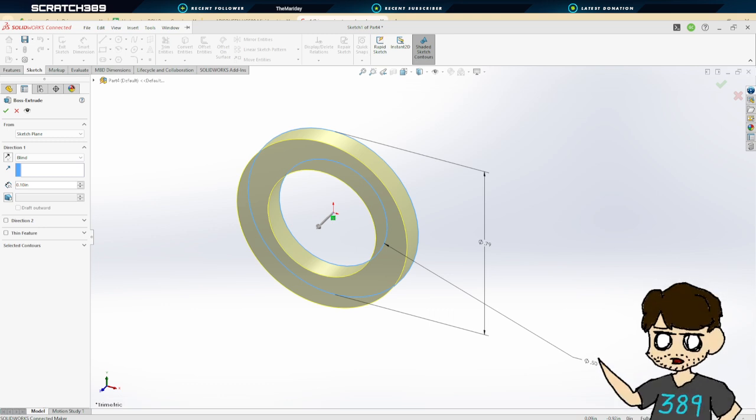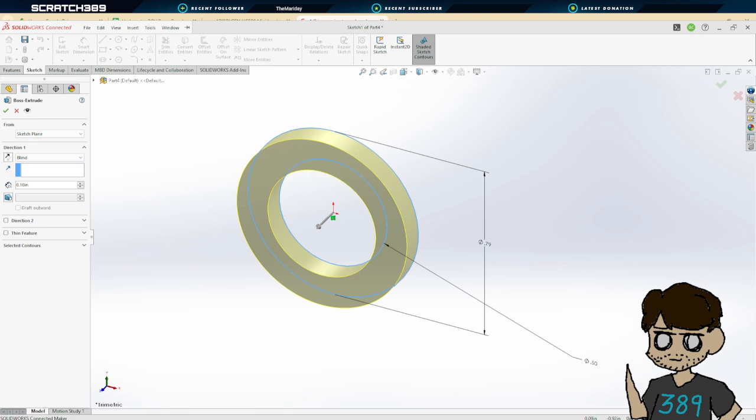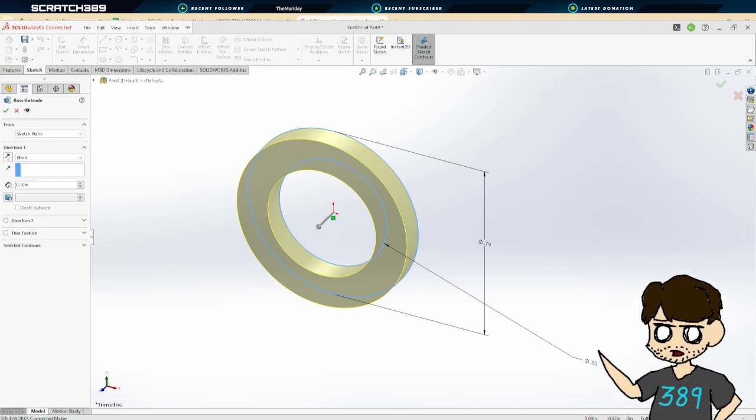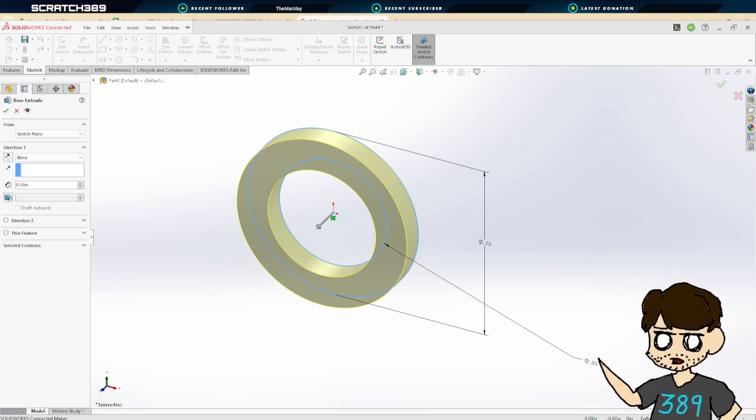Let's see. So, the total length of the T coupler is 2.835, and then we minus 0.885 times 2. Okay, so we're missing 1.065 inches. So 5 minus this. Copy. 5 minus base divided by 2. Okay, so we're gonna want a 1.9675 inch long piece if we're gonna make this exactly like half.